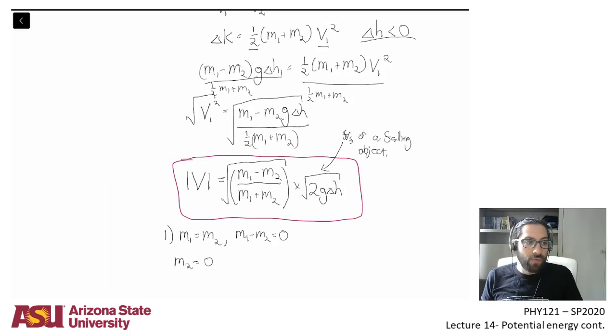I want to note, this did not involve drawing a free body diagram. This did not involve any assumptions whatsoever other than that these blocks, if one goes down, the other goes up, and they move at the same speed. So for example, if there was a spring in here, or if the tension was not the same, then you would have to deal with that in the problem. But because all of the work in this system is done by mechanical energy, we can solve this problem.